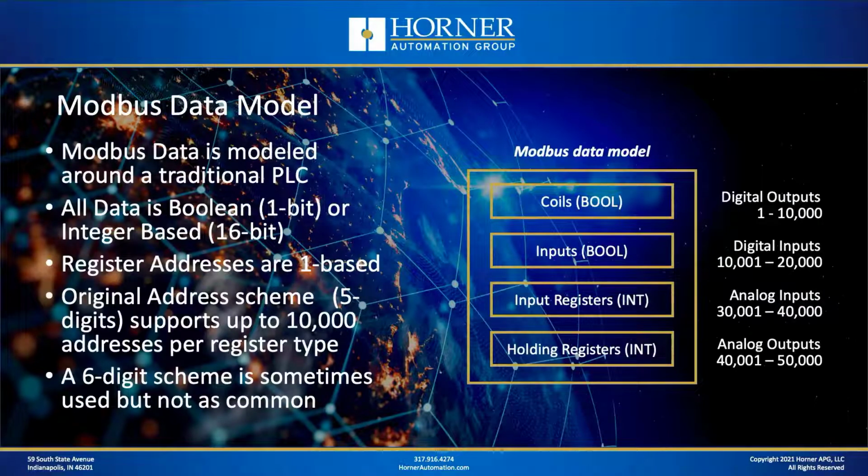Okay, let's talk about that Modbus data model, because when Modbus was invented, it was really modeled around a traditional PLC where all of its data was either Boolean based or integer based. Think about those early PLCs, and really PLCs to a great extent even today, where digital inputs and digital outputs are all Boolean based. Analog inputs and analog outputs are still, for the most part, integer based. So that's the environment in which Modbus was created.